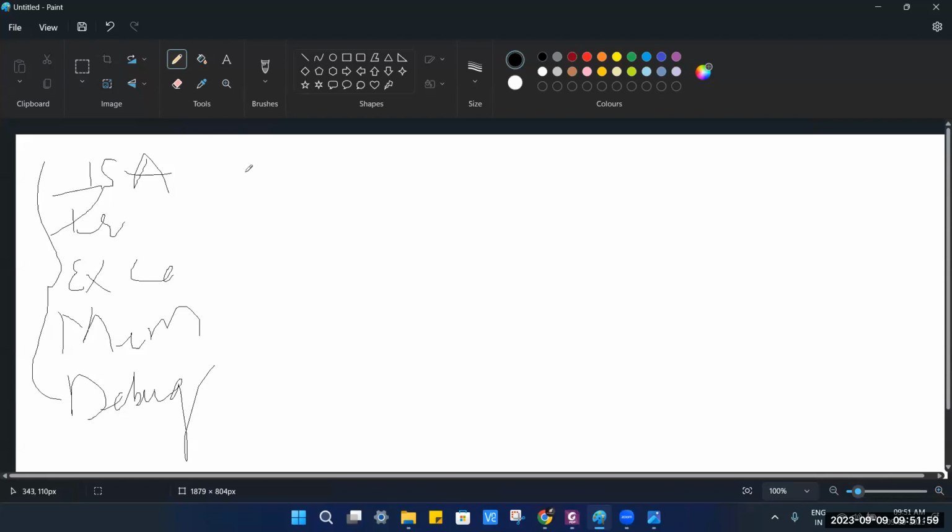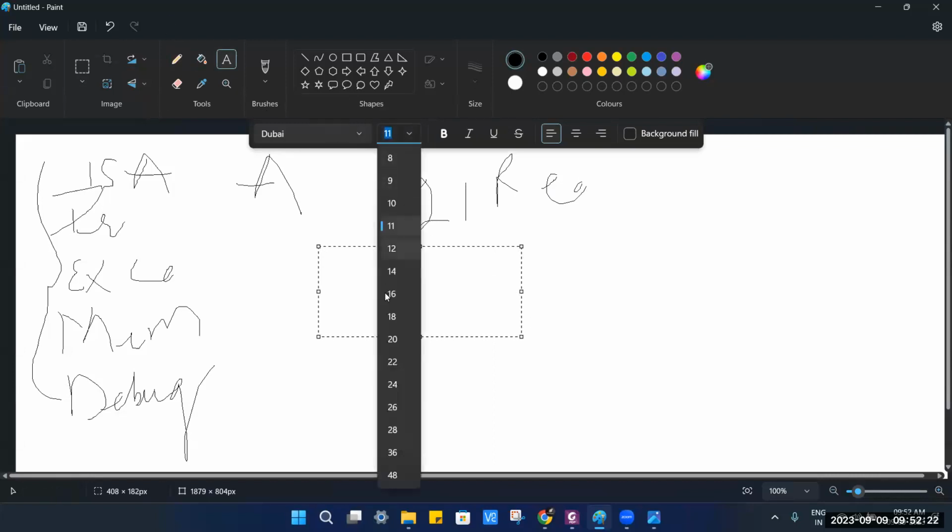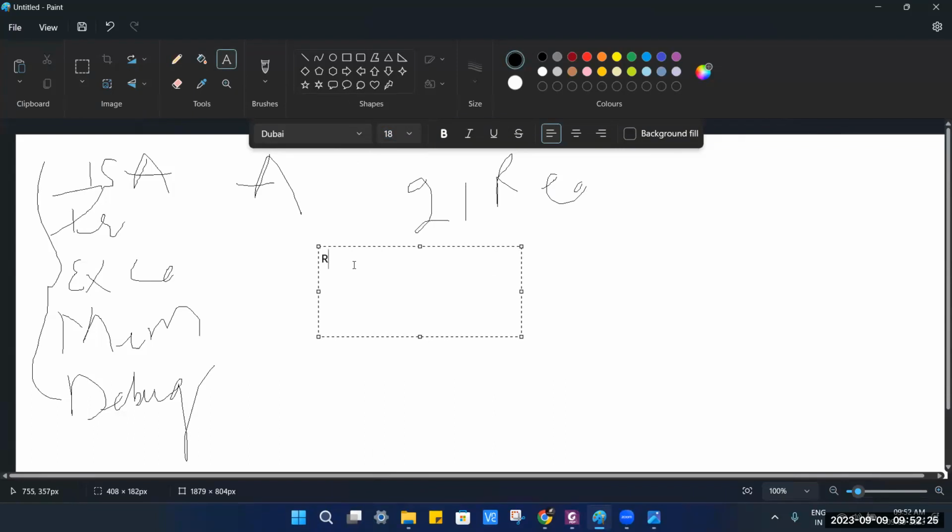In the ARM Cortex-M class, mostly everything is a game of 21 registers, and each is a 32-bit register because it is a 32-bit microcontroller unit. In these 21 registers, first, one second, I will increase the font. One would come from R0 to R12, which you might already be aware are general purpose. General purpose means mostly we will be using these for storing data, intermediate values, or function arguments.